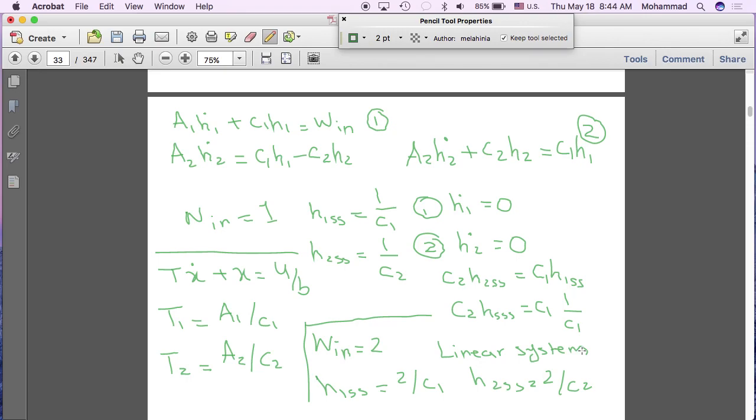So you're saying it doesn't really matter how much input you put into the system. The speed of the system is not affected by the value of input, but it's affected by the time constant. You're right. But that's not why we call the system time invariant. Time invariant means that the physical system itself doesn't change over time.